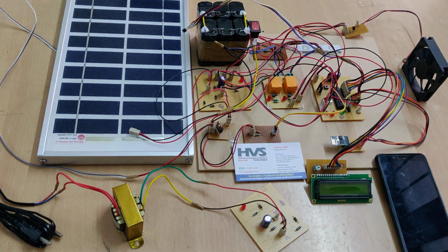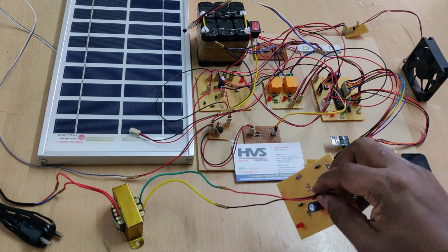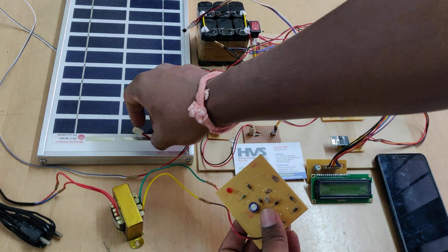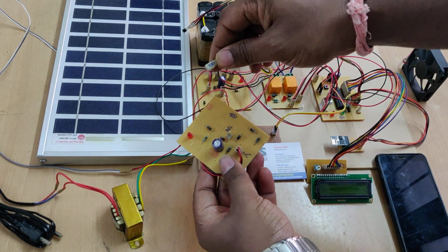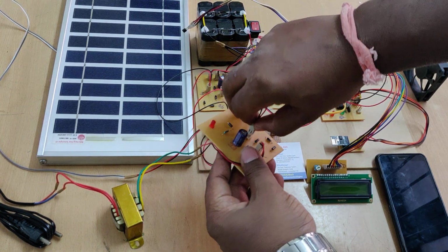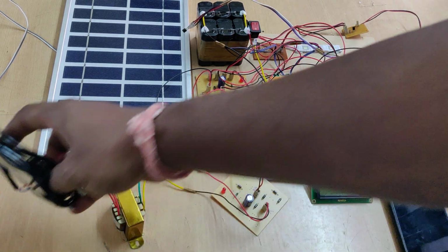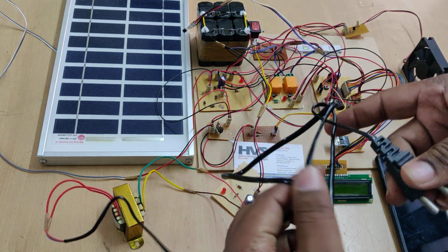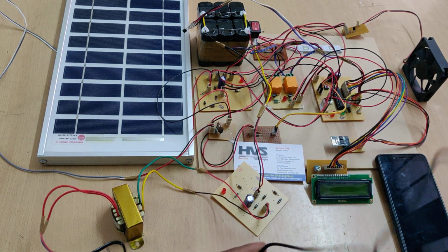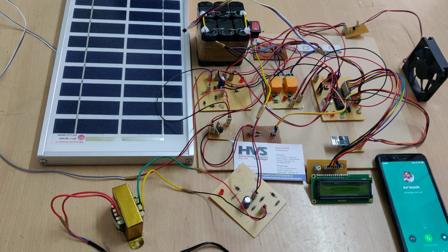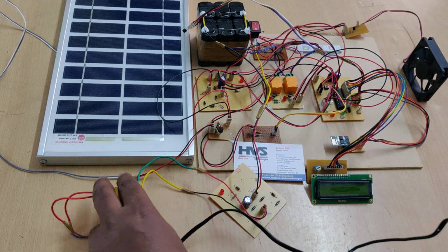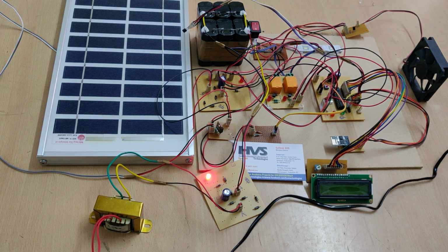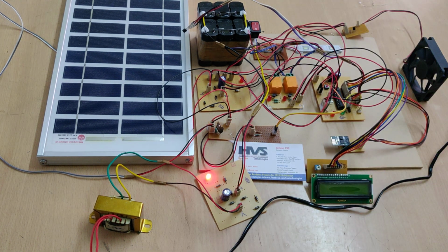Here we are providing one more alternate charger for the battery. Whenever sunlight is not available, we can charge this battery from this transformer. Here we need to connect B to this B, and after that give the power supply to the transformer. The transformer will step down the 230 volts AC to 12 volts AC, and after the rectifier circuit we will get a 12 volts DC power supply, and that 12 volts DC supply through this capacitor becomes pure DC, which is given as input to our battery. So now I switch on the charger.